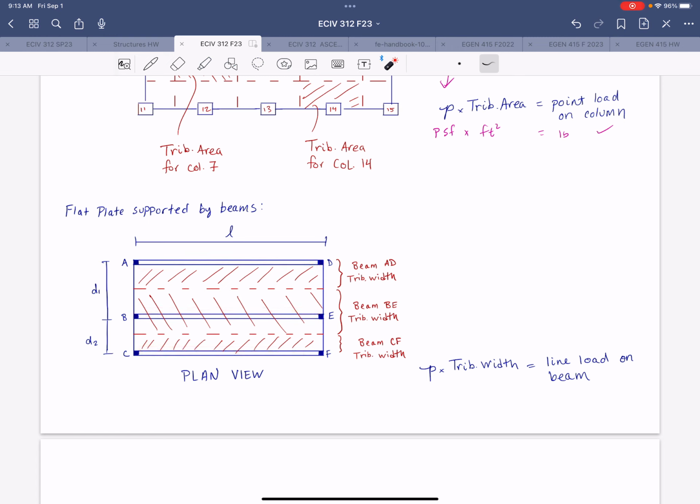So one clue that it's a one-way floor system is the difference in the spans. The distance between the beams is a lot smaller than the distance between any supporting element in that direction, right? And in your book, I think it gives you a ratio.